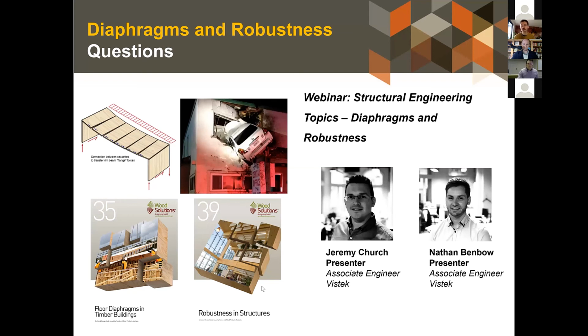So you might locate those at doorways where you've already got an acoustic issue or potential issue, certainly a weak point in the structure. Same with, say, bathrooms, making sure that the architecture has bathrooms backing onto each other. You might be able to put them there rather than from one living space or bedroom to another.